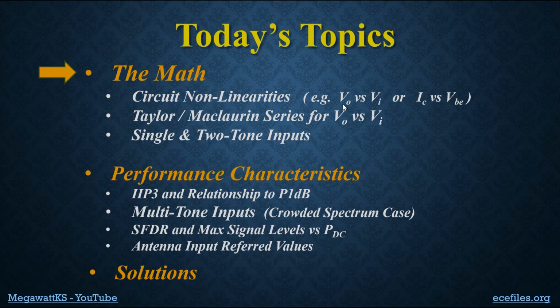We need to characterize the output voltage versus input voltage of the amplifier. Ordinarily, you multiply the input by the gain and you get the output, right? But that's for a so-called linear amplifier. Now we're talking about non-linearities. Then we're going to talk very briefly about Maclaurin series, which is a special case of a Taylor series, if you remember any of your calculus. If not, don't worry about it. We'll explain it. And then we'll look at what happens when the input is not a single sine wave, but is rather a two-tone input, so two sine waves together.